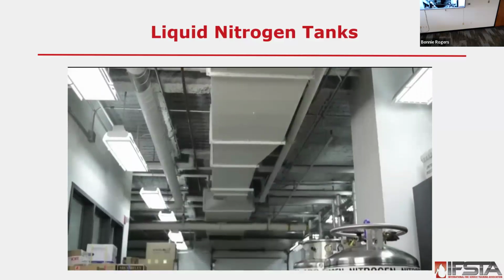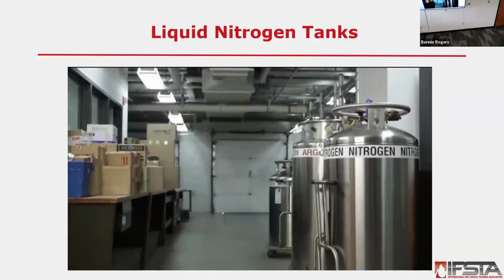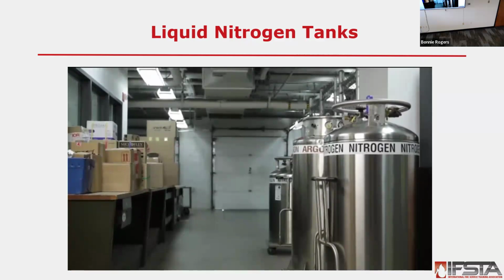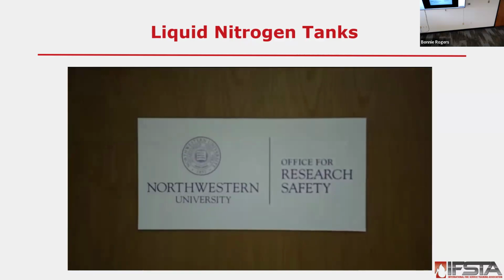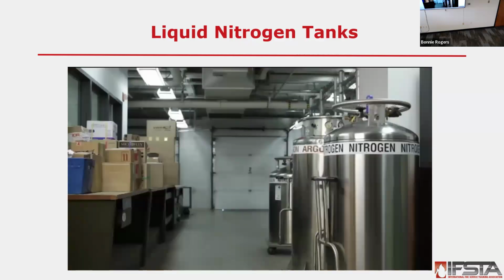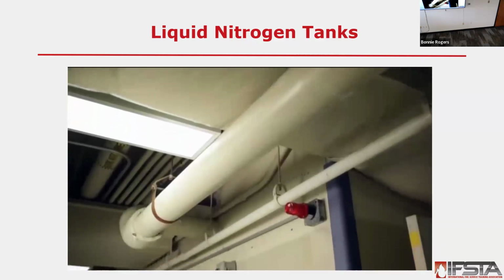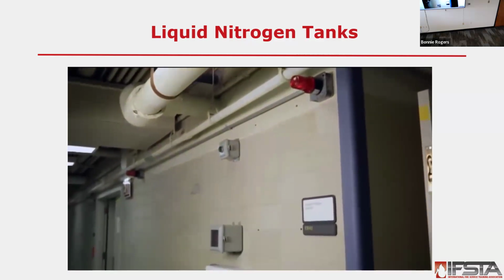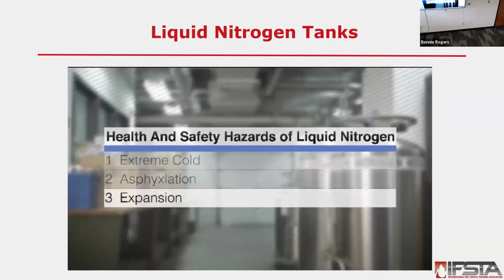Since nitrogen is odorless and invisible, fill and store nitrogen containers in well-ventilated areas. Contact your safety office to determine if a space where liquid nitrogen will be used or stored is well ventilated or may require oxygen depletion alarms.